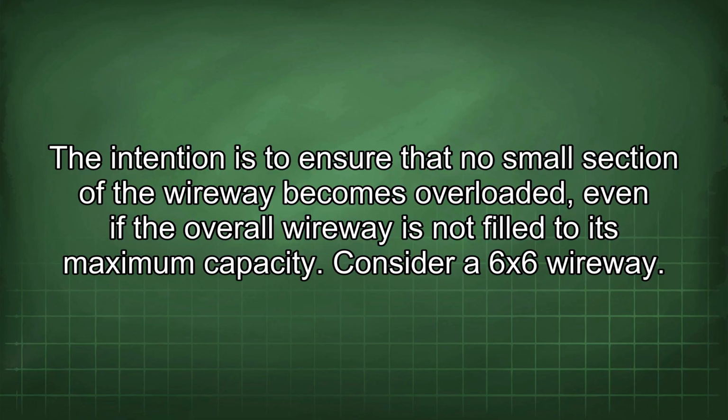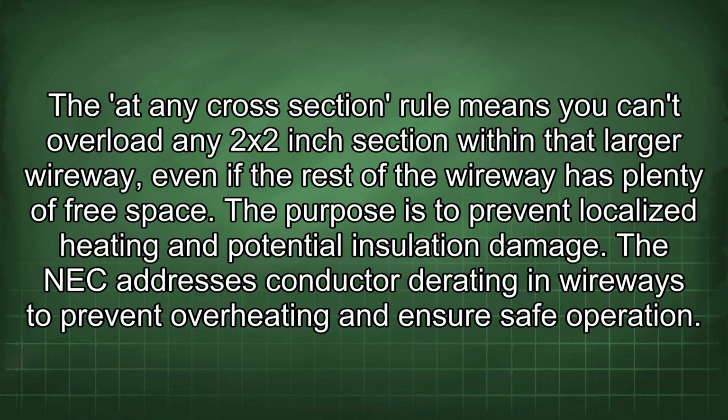Consider a 6-6 wireway. That any cross-section rule means you can't overload any 2-inch section within that larger wireway, even if the rest of the wireway has plenty of free space. The purpose is to prevent localized heating and potential insulation damage.